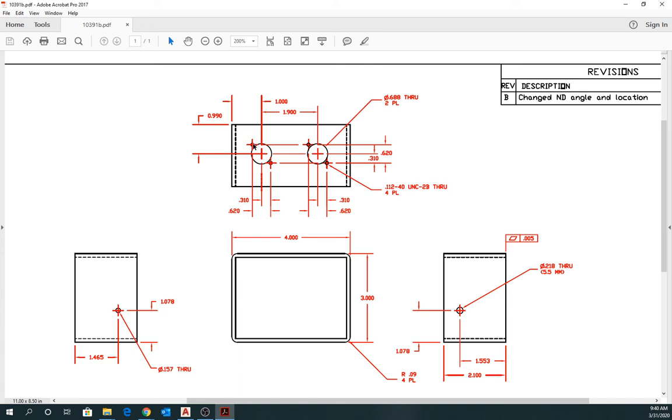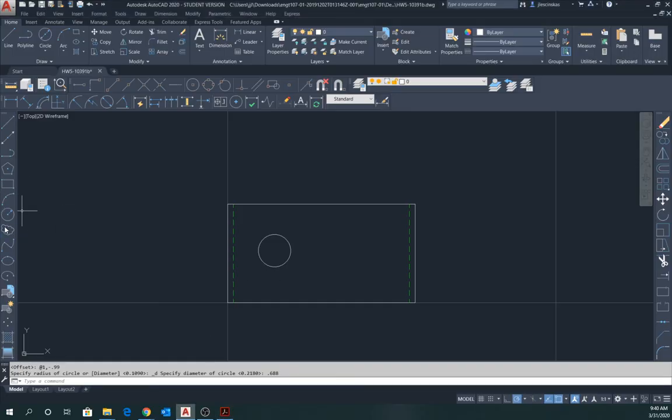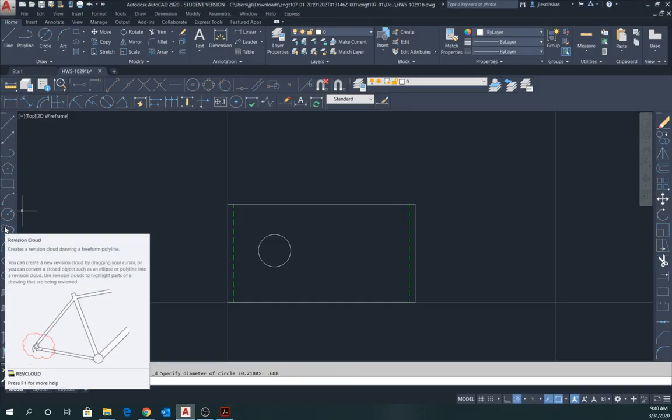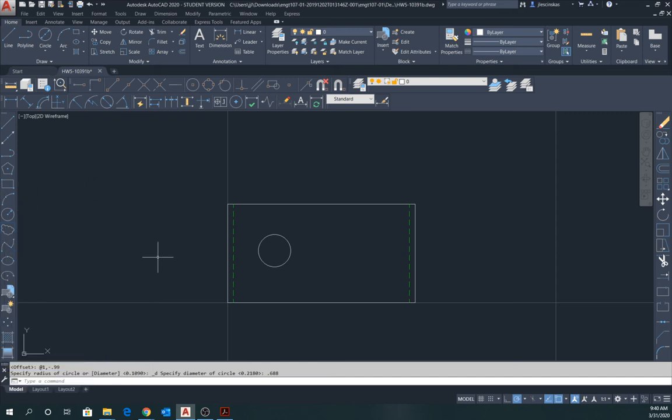To the upper left and to the lower right. So let's go back and put those in. And those hole diameters are actually 0.112. So again, circle diameter, snap from. We're going to snap from the center, and here we're going to go minus 0.31, comma 0.31. So we're going to go negative x, positive y, hit enter.